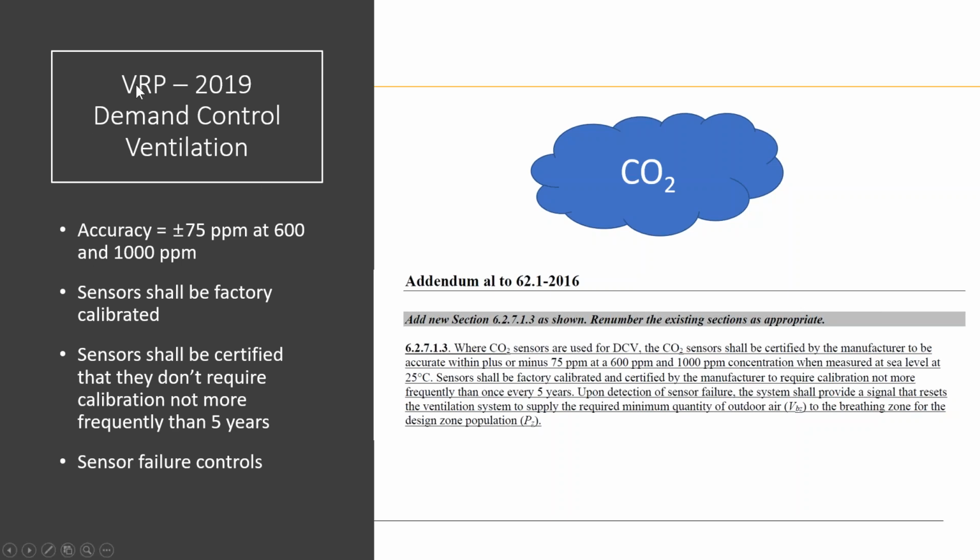so the full outside air needed, and then you can in operation decrease your outside air using the demand control ventilation, but that only takes care of the pollutants supposedly generated by people. So you have a very small margin for offices of how much you can reduce your ventilation rate. So for office, you need 5 CFM per person, 0.06 CFM per square foot. So the portion that you can play with using demand control ventilation is only the 5 CFM per person. And you need to be able to adjust it dynamically.